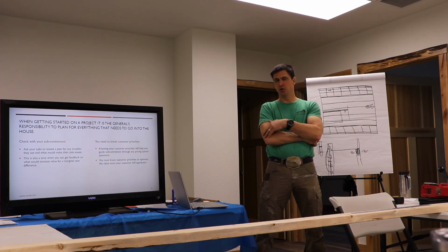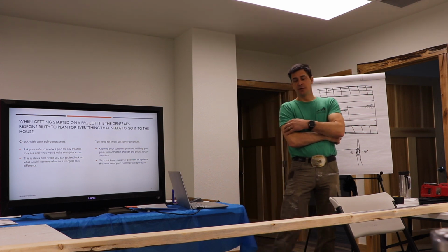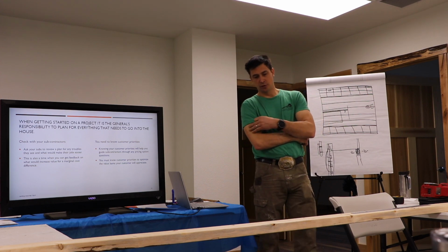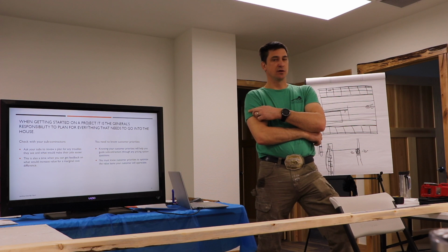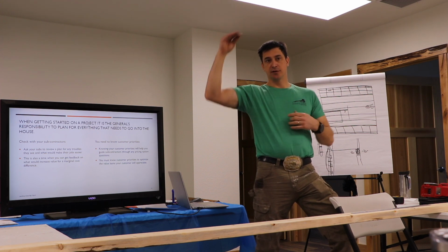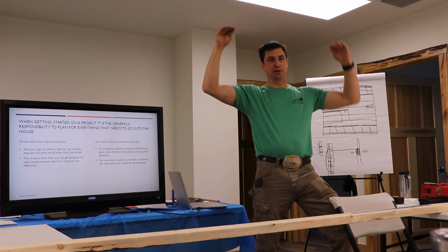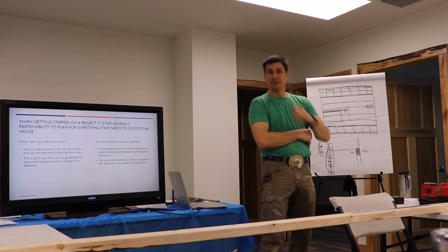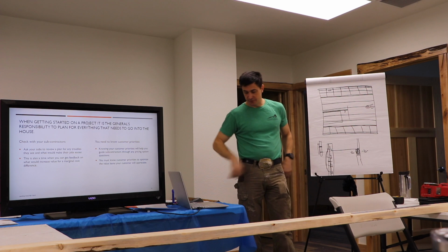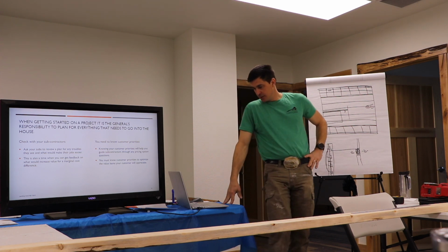Generally, they'll give you a top of window height. As a general rule, if the plan does not give you a top of window height, I'll usually put my top of door opening and top of window openings the exact same. Just a good rule of thumb.